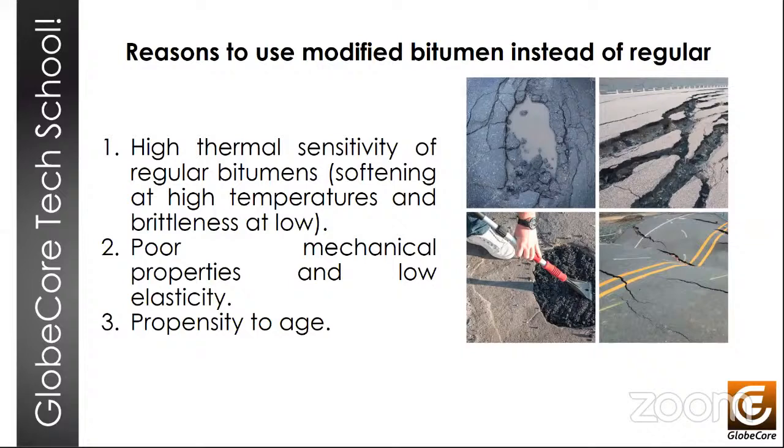For some time, advances in science and technology were sufficient to meet the requirements of the road construction industry, but traffic intensity constantly increased, as did the load on the road surfaces, and these loads cause destruction and deterioration of the roads. Despite the fact that oil distillation technology was improving all the time, the quality of bitumen as a distillation product actually only got worse, and the deepening of oil refining in order to increase the output of fuel components, lighter fractions, led to a deterioration in the quality of bitumen.